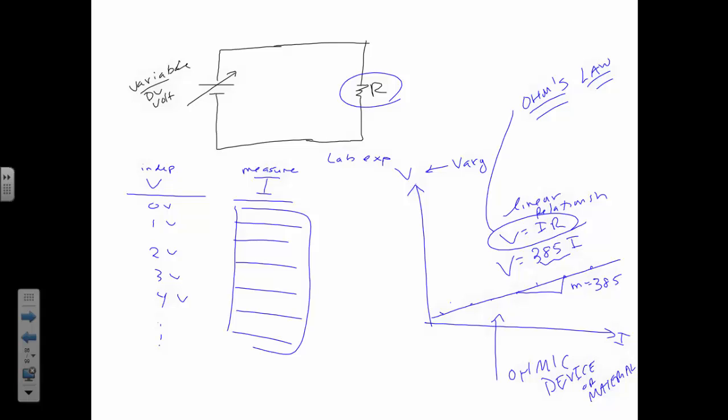And if you mix different impurities into it at certain ratios, you can vary the amount it conducts, and you can very carefully in a manufacturing environment control exactly what the values are here. Like I said, over my drawers over there, I have these exact same shaped devices that go from, I don't know, a couple ohms up to a couple million ohms in the same shape of device. And all they're doing is varying the impurities in this composite of materials, which carbon is one of the key components in, to make it more or less resistance. And they can control it very, very accurately.